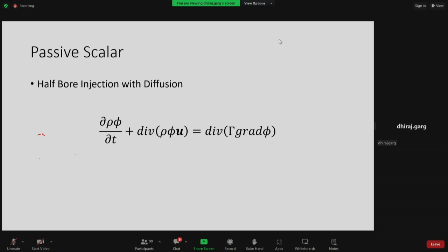For example, you are specifying velocity at the inlet. Since it is not changing, that itself means there is a continuous flow, right? Okay. So when you are specifying phi equal to 1, it means the tracer is coming continuously at the same concentration, unless you give some formula to change it with time, that after this, it changes to this or this. Otherwise, it will continuously be injected at the same concentration.